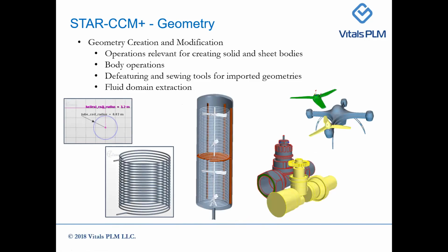And in STAR-CCM+, we can also create and modify the geometries. As you can see here, you can create a spiral tube, and then the whole geometry here is built in STAR-CCM+. So you can build some complicated geometries in STAR-CCM+ itself. And we can easily extract the fluid domains and also copy and paste around the multiple bodies.